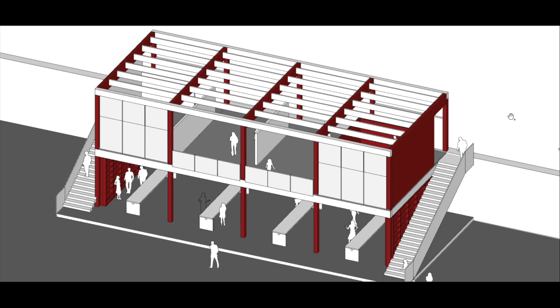What does that look like as one potential option when we're done? Well, we could have the CLT walls on the two sides that are providing the lateral bracing in that direction, open all the way through. In this case, you can see it's option 1B, where we have girders and purlins.